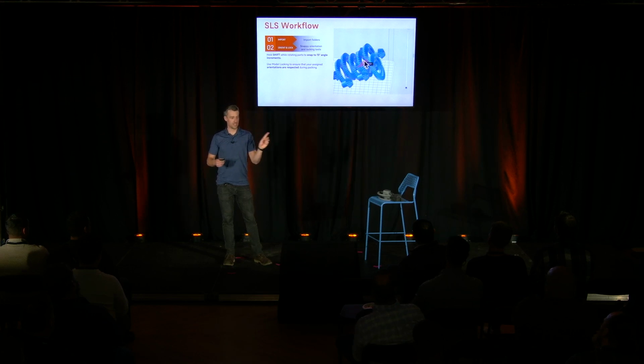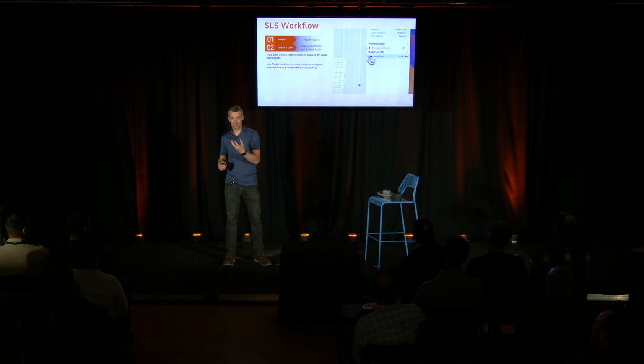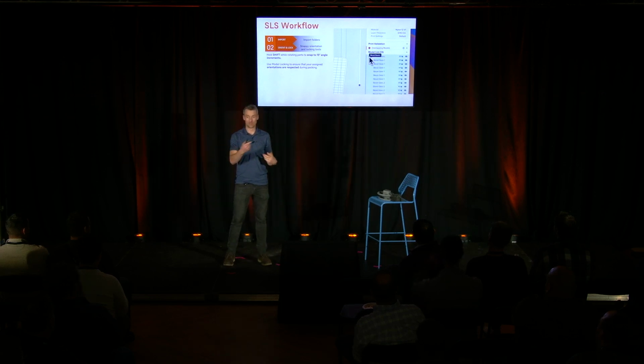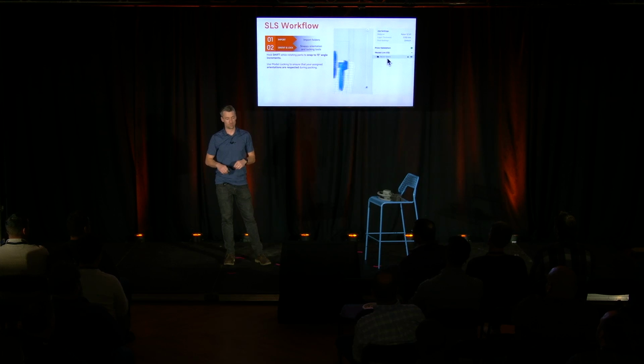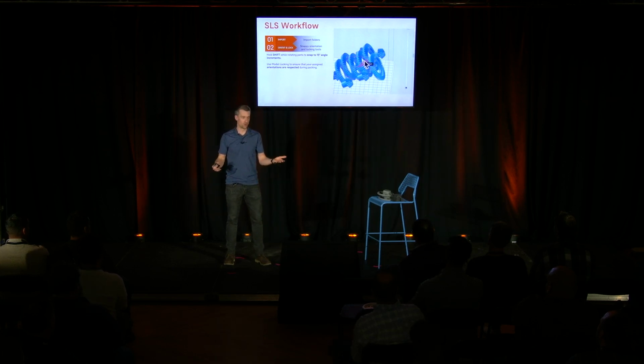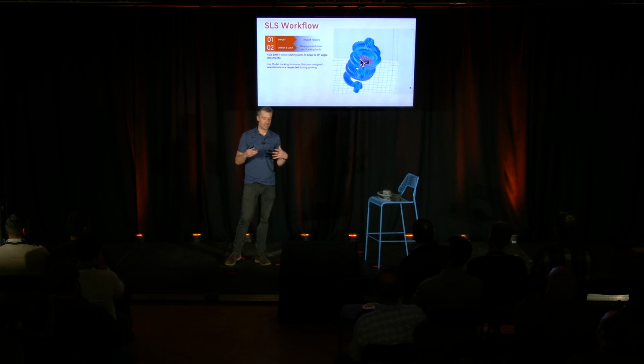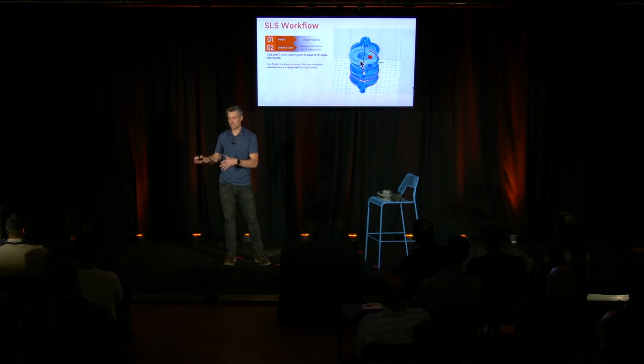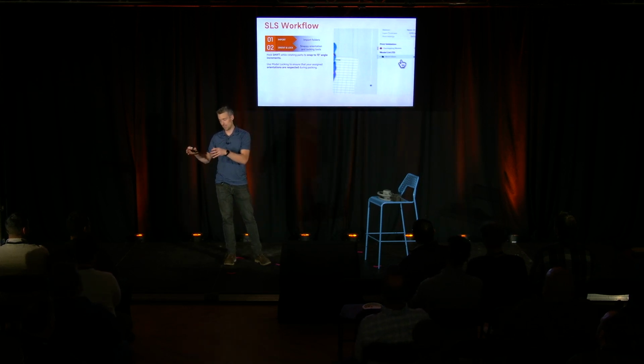Just as a reminder, the X plane goes across the front of the printer, the Y goes into the printer, and the Z goes up the printer. So you can lock it just in the XY plane, so it'll just rotate around. You can lock it in the X, Y, and Z, so you're going to have 0 rotation, but you'll be able to translate about the build chamber. And the third one is complete locking, so no translation, no rotation. And the benefit here is that you're setting a number of constraints on the system itself, on that part.